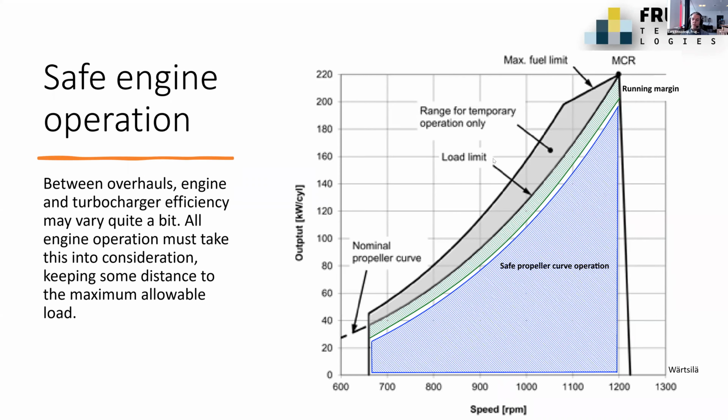This bit over here is actually a snip from a manual from a Wärtsilä engine, which shows the area of operation that the engine sort of accepts. There's this notion that you can drive the engine at a certain amount of RPMs, and you can force a certain output power from the engine, which is basically what you get as you increase the pitch of the propeller.